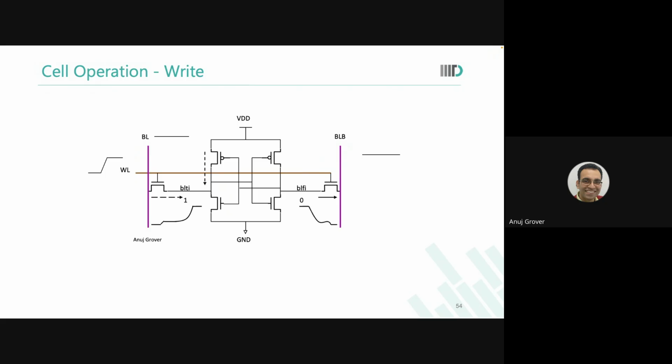You can do that. But my experience tells me it wastes more time. But in a particular condition, in a particular situation, that is what may be required. For example, if you want to make an extremely low power memory and you want to use the advantage of sparse matrices. All our CNNs are hugely redundant. Hugely. In all the weight vectors that come, most of the things are 0. Today we have advanced methods to compress neural networks, so there is not that much 0 now, but initially there was a lot of sparsity in it.